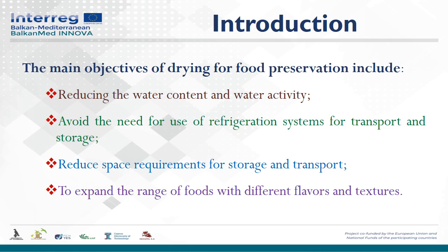The main objectives of drying include preserving foods and increasing their shelf life by reducing the water content and water activity. This is related more with the pathogenic microorganisms, because if the moisture or the water activity is at high levels, this may create good conditions for the development of microorganisms that might spoil the food product. Another objective is to avoid the need for a refrigeration system for transport and during storage.